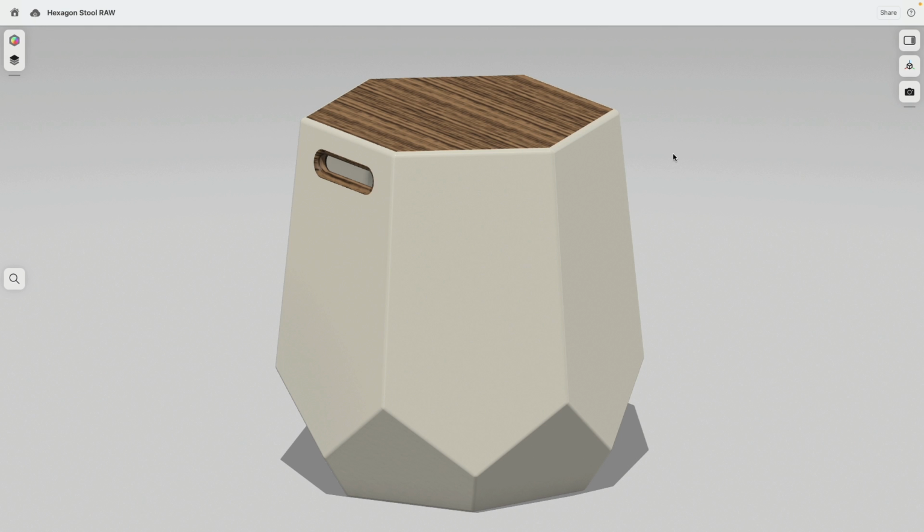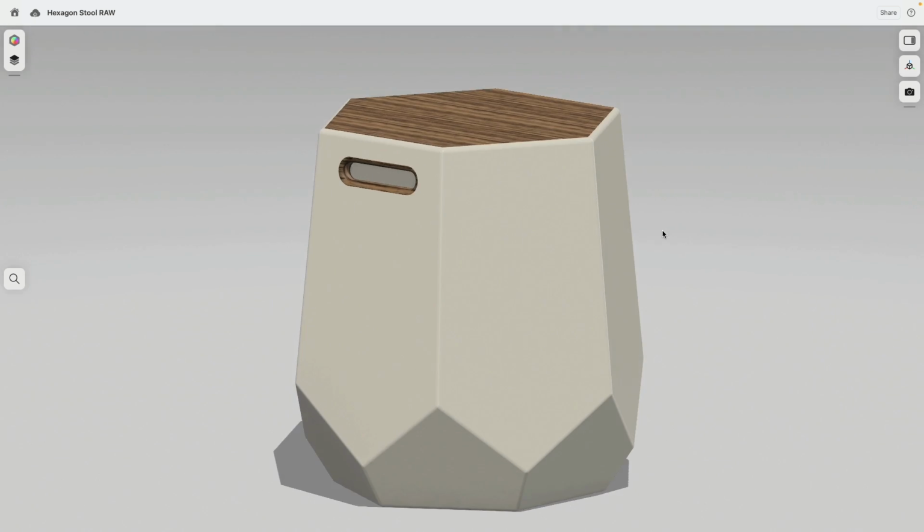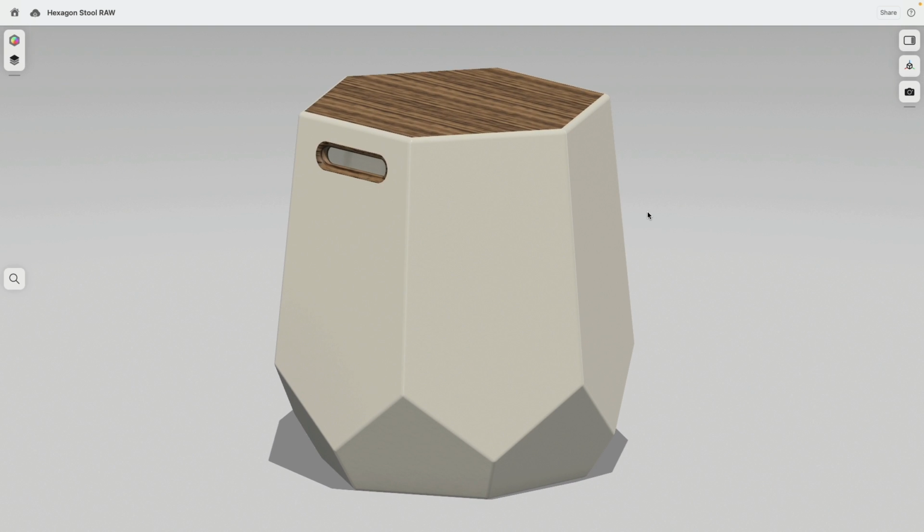So out of 2 sketches, 2 extrusions with a draft, and then we do a Boolean intersect, then we round the edges, we shell it, make a new sketch on the side, cut the openings, detail it, add materials. Easy peasy. Okay, you know what? This video is done.